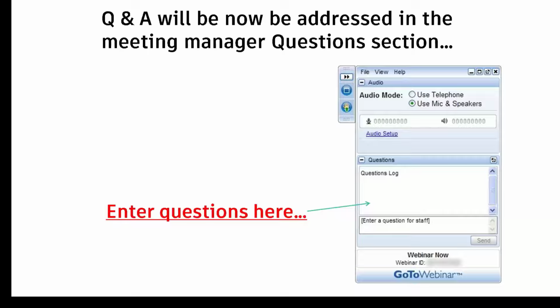With that being said, is there a specific guideline for every single model? No. What we're really watching for is, is the mesh itself uniform without large amounts of deviation? And in one of the solves that Kendra actually ran, you could see there were some warnings that came up during the engine solve. Where it was basically saying, there are elements in here that are beyond the limits of what you've specified as quality definitions for your mesh.